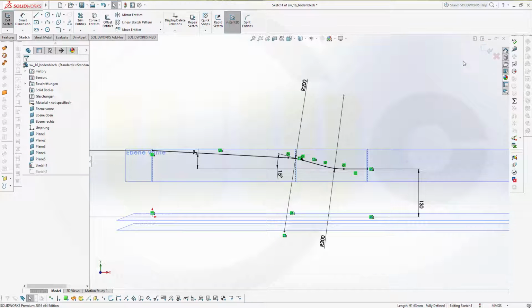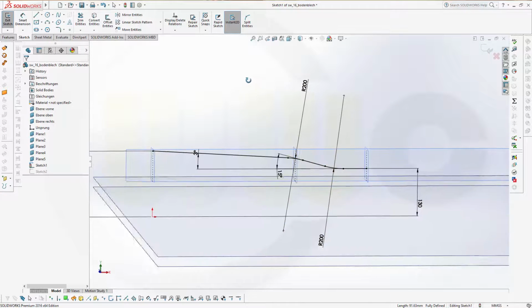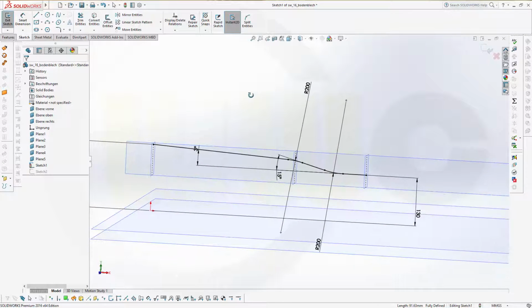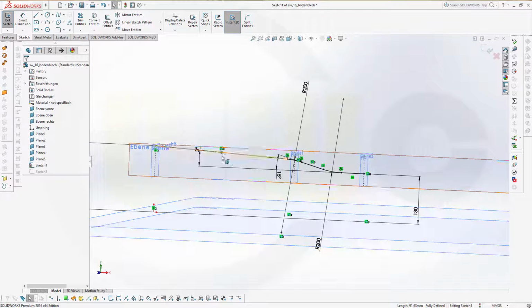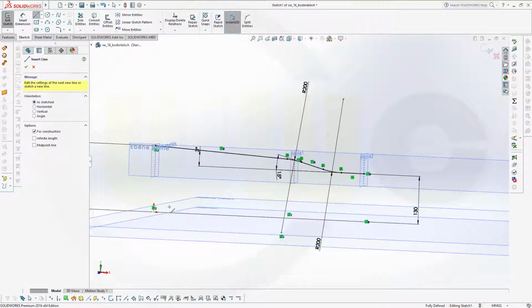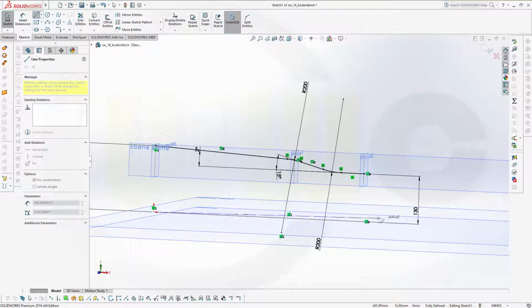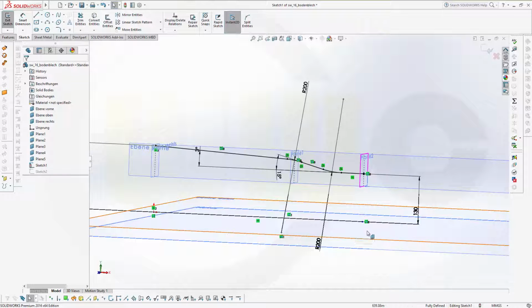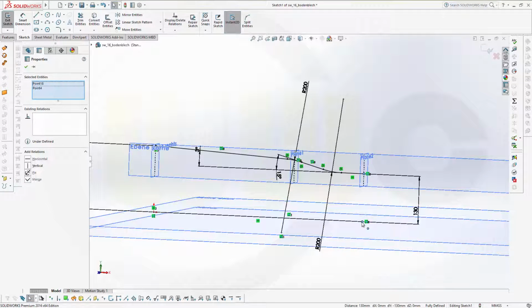Leave the sketch. I also need an axis. I could have done the axis in this sketch, so yeah, I will do it in this sketch. Make it a center line which goes from this point maybe up to this one, and these 2 points should be aligned. Okay,